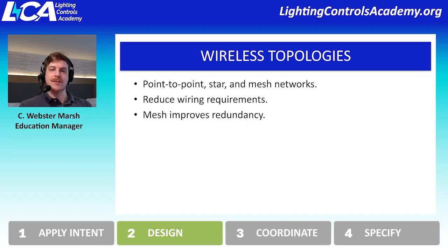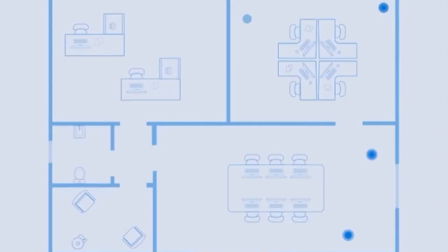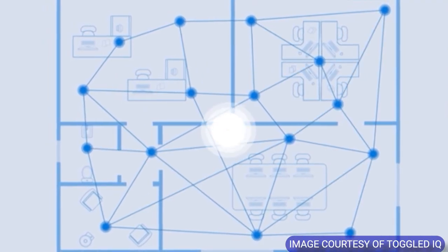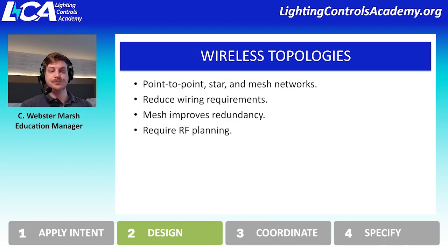So it might not be as strong of a data packet, meaning it doesn't have as much complexity or information as a wired solution or even a star wireless solution. So just keeping that in mind. But there is an argument to be made that a mesh system has a redundancy within it that allows it to become a more robust communication point.